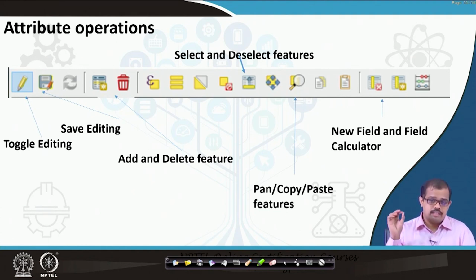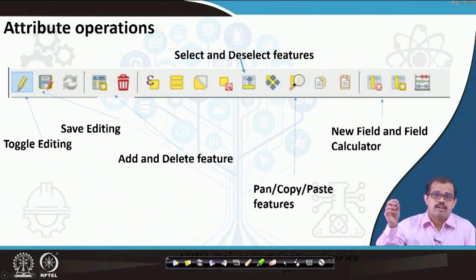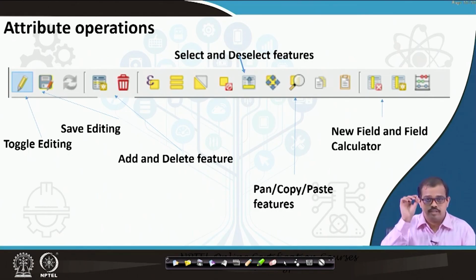With that column, I'll start the field calculator. I'll calculate the area. It is just like this, $area, like you do in your Excel sheet. So it basically calculates the area of this polygon. Based on the geometrical shape, it can calculate the value.